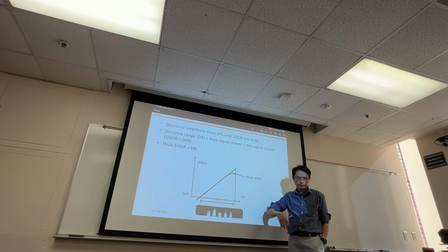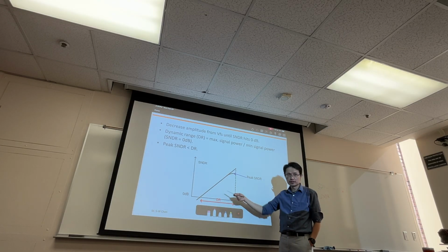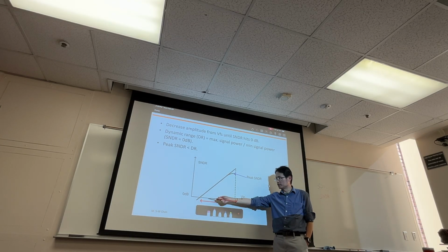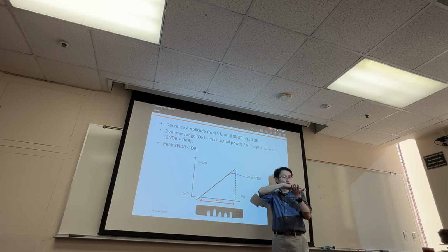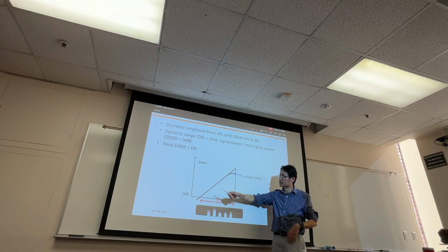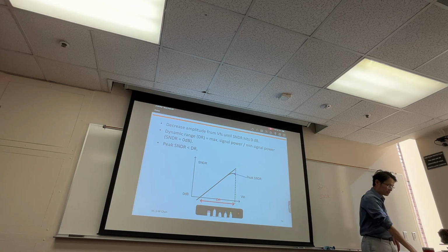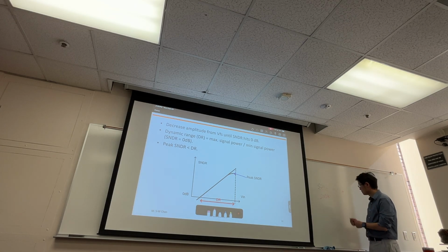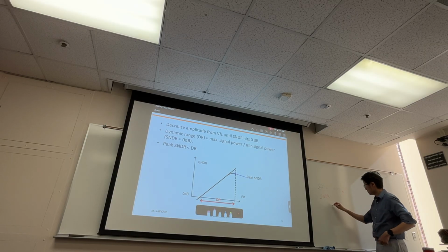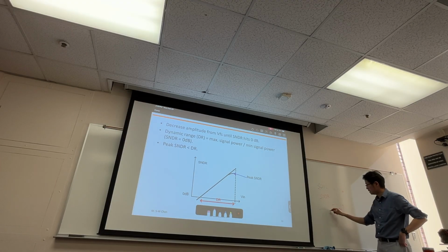What you do is measure your ADC and keep increasing your input amplitude, let's say with a sine wave. Do you agree that my SNDR will keep increasing as I keep increasing the input amplitude?